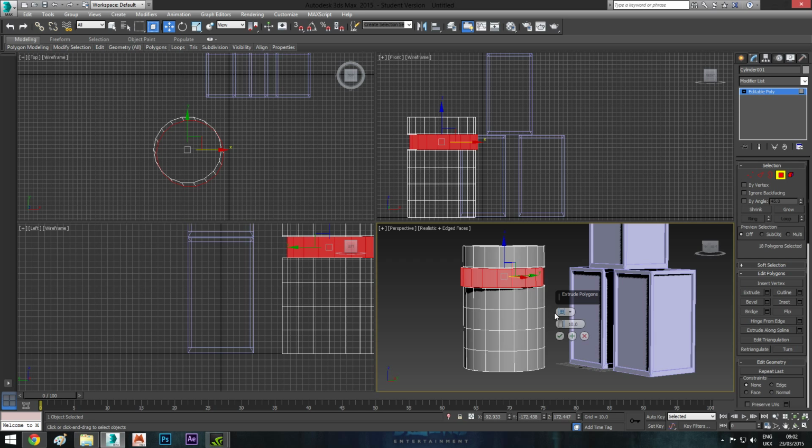Now as you can see, it's going the one direction. Okay, we don't want that. We want it to go in itself, so what we do is we hit local normal. So now you can see it's going in and out, and we want to just bring that in a wee bit. Just a wee tiny bit. So we'll say 11. 11 will do the job. Maybe not 11, maybe we'll put it minus 13. Okay, that'll do.